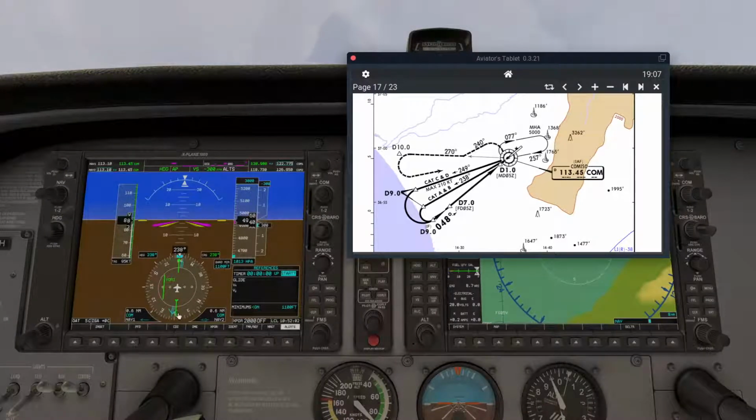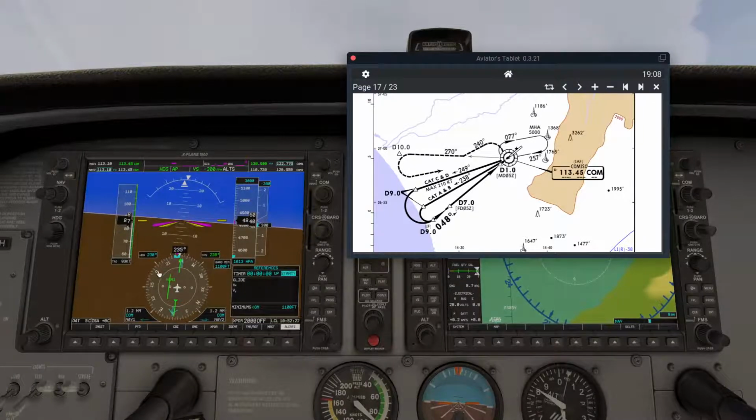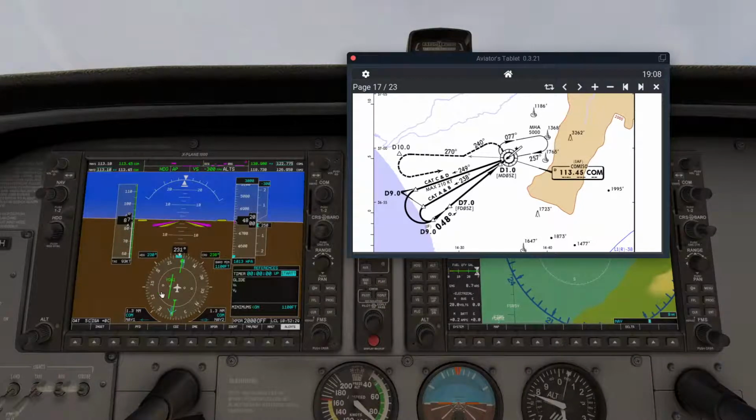After station passage, proceeding on a longer distance than 1 nautical mile and check the CDI. It has started to center, but there is, as I guess, some correction to the left to make it easier to center the CDI or course deviation indicator, descending to 3,000 feet.